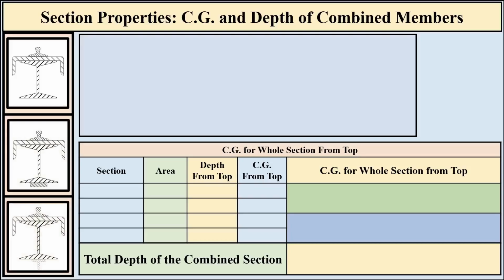It is important to note that while the crane rail is shown at the top of the assembly, it is not considered a structural part of the gantry girder for strength calculations. The rail is a mechanical wear surface. Therefore, when calculating the section properties like the area or moment of inertia, we focus only on the I-beam, the channel, and any additional plates or tees.